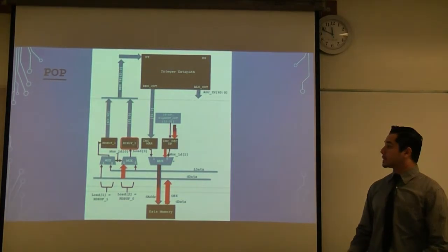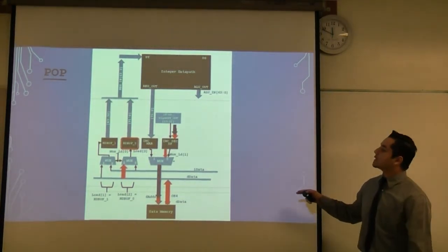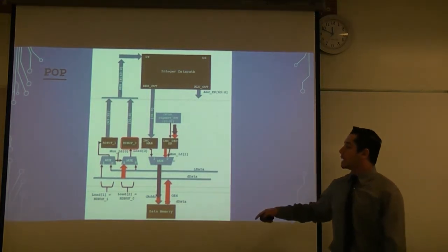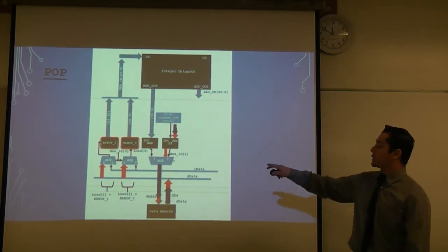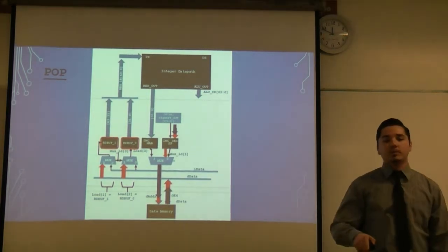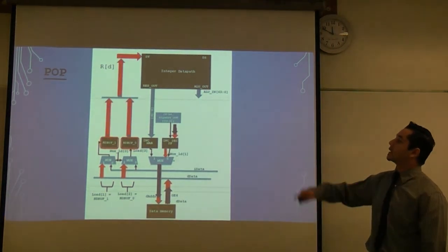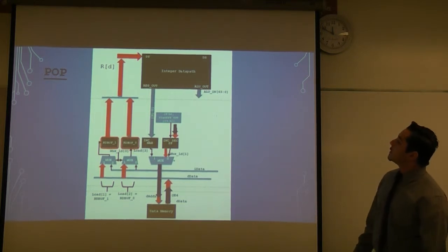On the second state, you're going to be doing the same thing again. Now you have decremented, so now you're at the one right on top of that. You're going to be trying to read the upper 32 bits, and that happens here. So now officially you have both the read buff 1 and read buff 0 loaded. And now in the third state, you're going to be writing it back to the register destination.